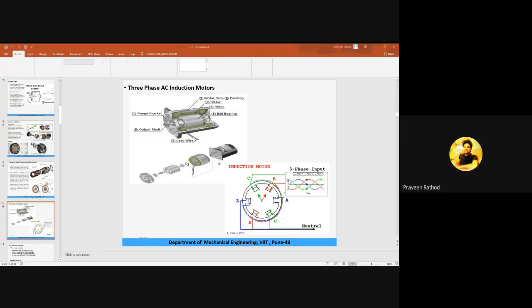So when I am talking about the clutch, it is entirely unnecessary in the electric vehicle. The torque speed characteristics of a motor are very different when we compare with a normal engine. In the first chapter we studied the torque speed characteristic with the help of a graph, how the speed varies when the torque increases or decreases as the vehicle speed varies, in the case of the gasoline engine as well as the electric vehicle.